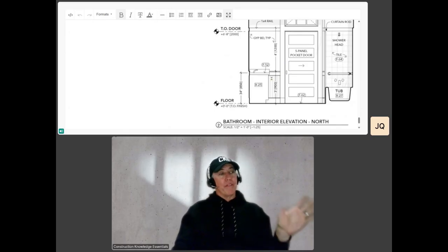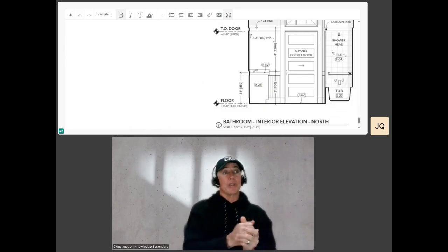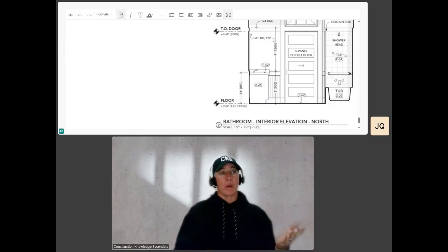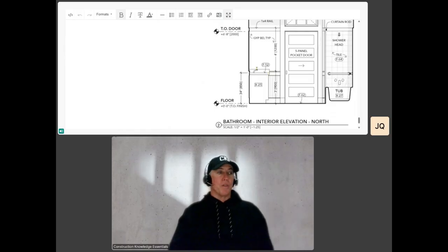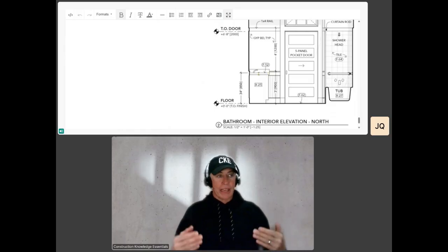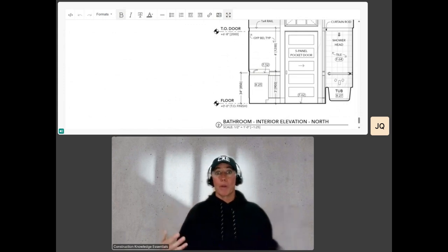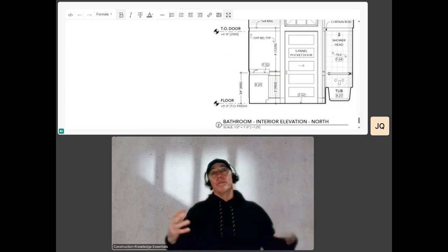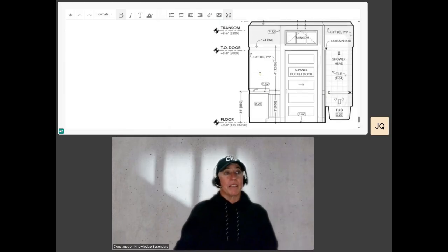Then if we look over at the vanity, you have X25. Again, that's going to be on the finished schedule or millwork schedule. And it'll say X25, and you'll say, what the heck is X25? And that's that cabinet, right? Just as the finish is F52 for the top of that vanity. That's calling out that finish and saying, hey, this is the finish we're using. It's going to be either marble, or it'll be a terracotta, or a granite, or who knows? There's a million different things. Mica, whatever that design has been, and you can then exchange those for different things.